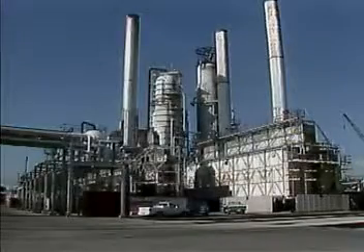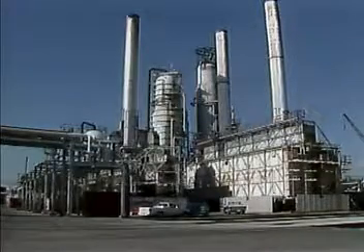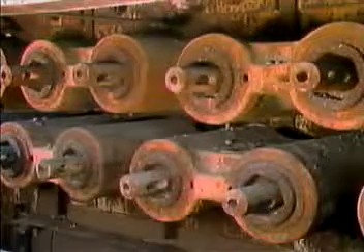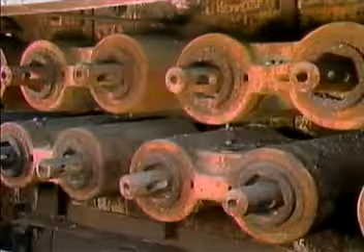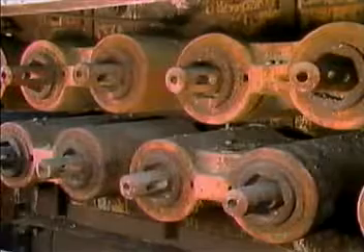Regardless of the design of the furnace, the tube arrangement has to allow for a continuous flow of process fluid. For example, these tube ends are connected with tubing bends. In other tube arrangements, the tubes are connected together by enlarged sections of pipes called headers instead of tubing bends.